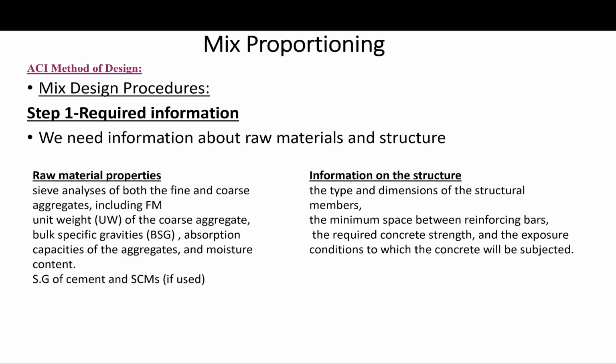It may be handy though here, as I mentioned about aggregates, to go back to refresh your memory in certain parameters about the aggregates, the bulk specific gravity, the absorption, and the moisture content. You will need that when we do the adjustments for moisture for the aggregates.